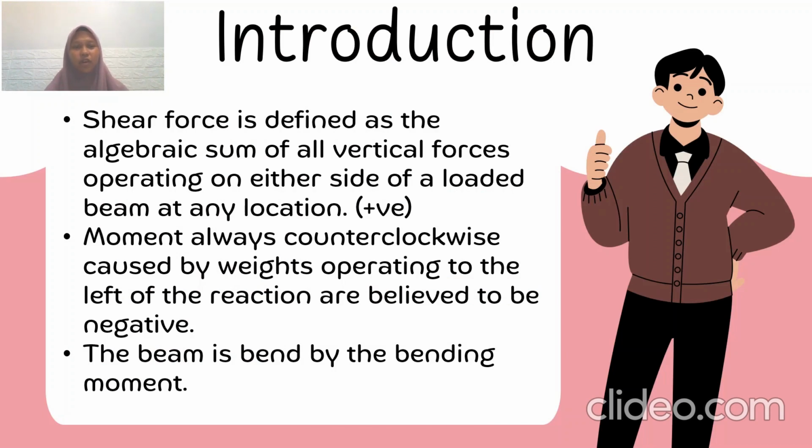The introduction for this experiment is about shear force, which is defined as the algebraic sum of all vertical forces operating on either side of a loaded beam at any location, which is positive. Moments that are always counterclockwise, caused by weights operating to the left of the reaction, are believed to be negative. The beam is bent by the bending moment.